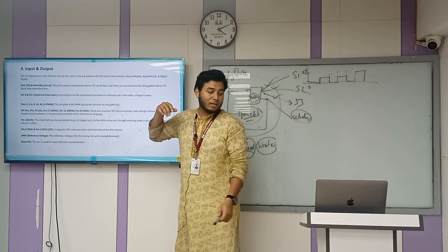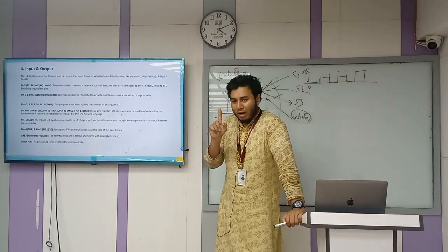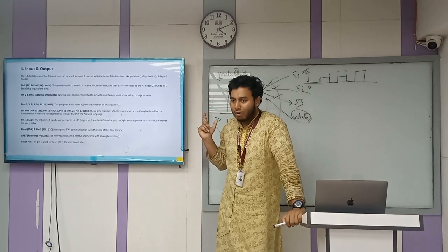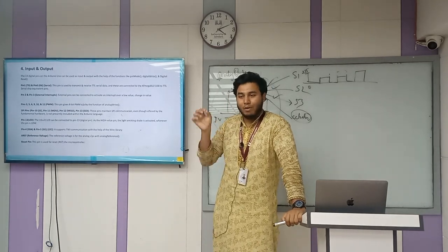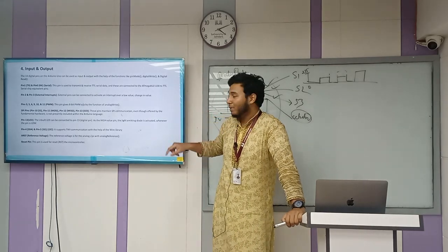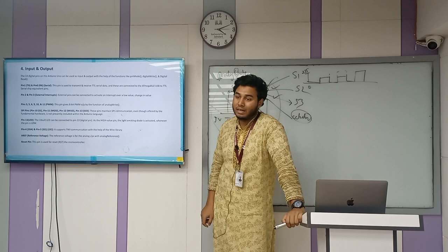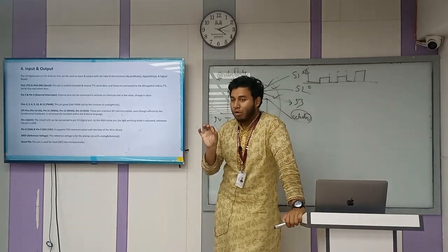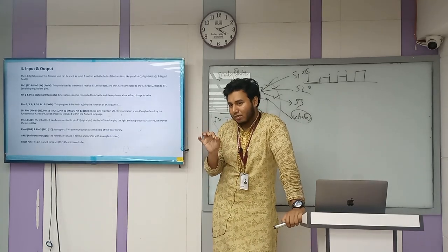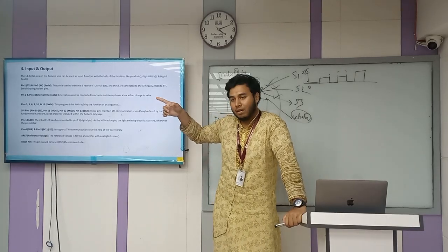If you want to work with two or three LEDs, that's fine. But if you want to work with one LED and you don't have one right now, you don't need to worry, because there's a built-in LED connected with the Arduino, and that pin number is 13. So when you write the proper sketch, you have to declare that pin number.